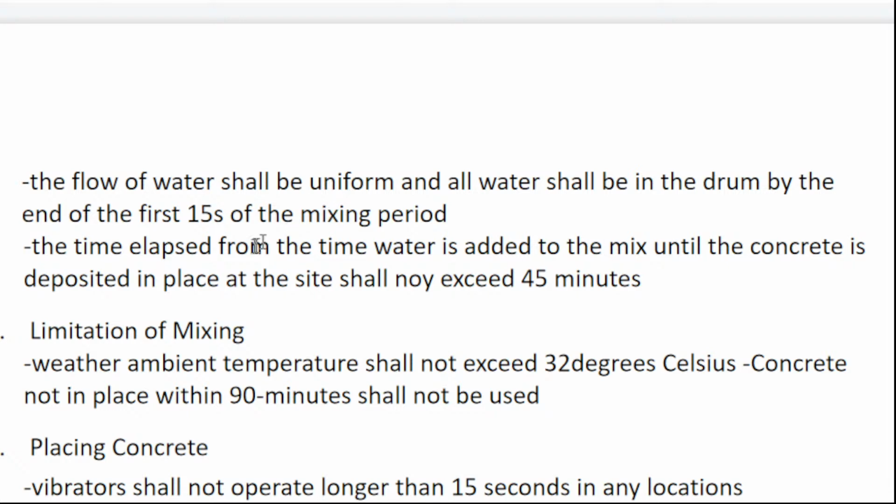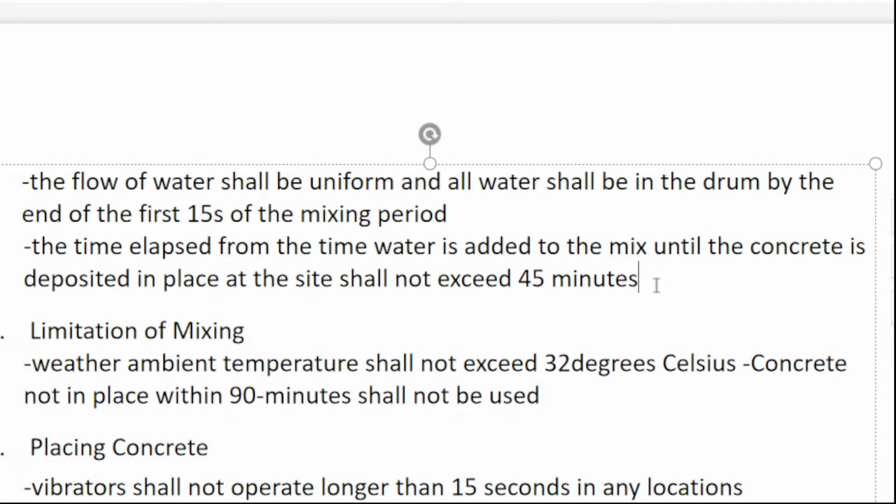in the drum. Okay? The time elapsed from the time water is added to the mix until the concrete is deposited in place at the site shall not exceed. Another typo error. This is shall not exceed 45 minutes. Take note, 45 minutes. Okay? From the time the water is added to the mix until such time that this is being placed. 45 minutes. This is the acceptable. This is very critical and is being followed right now.